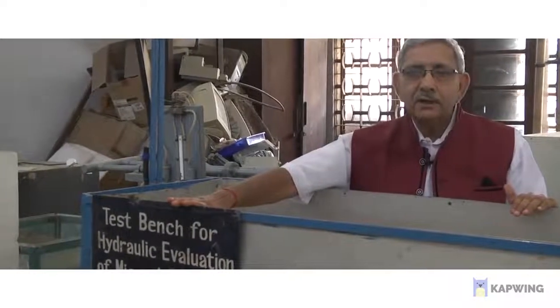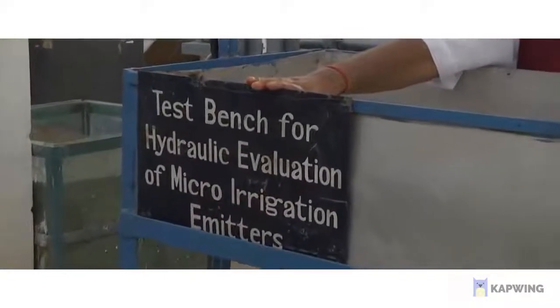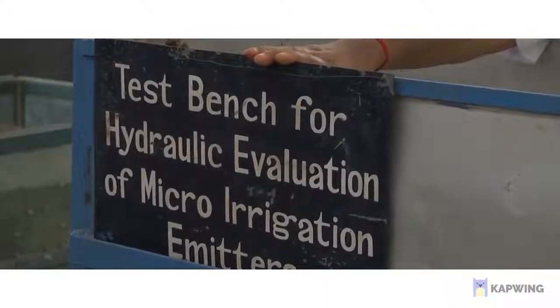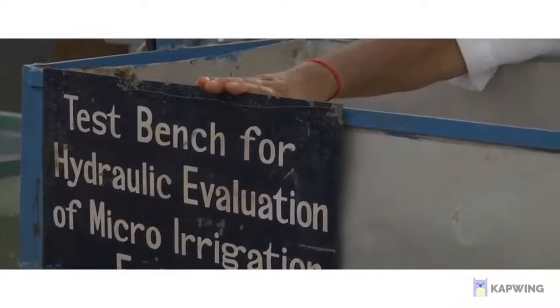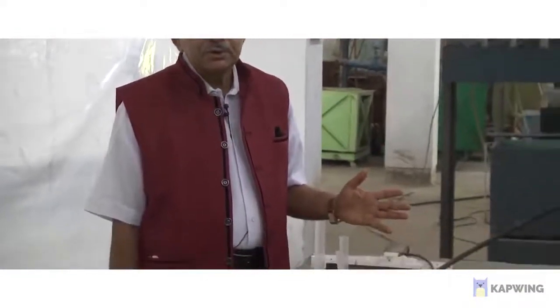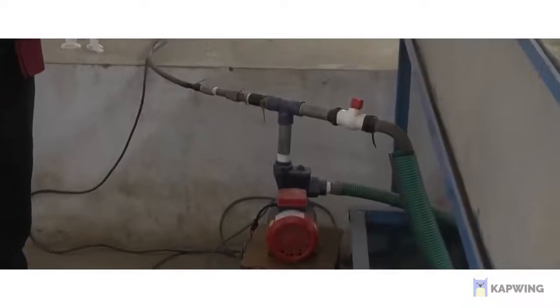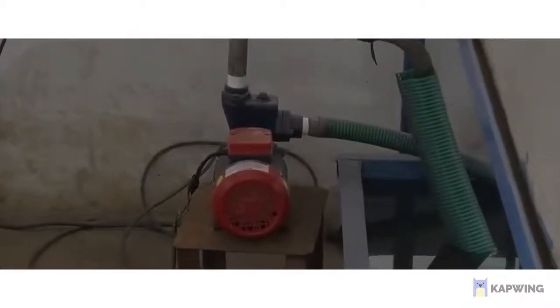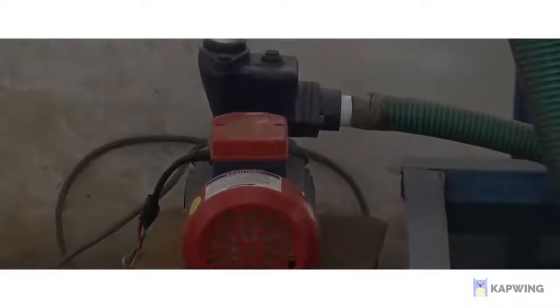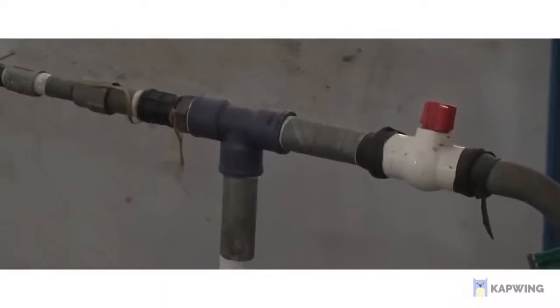This is a hydraulic test bench for evaluation of drip emitters. This hydraulic test bench is meant for finding out the emission uniformity of drip emitters. So, a pump is used to collect water from the source, then water comes through a set of drip irrigation filters, then it goes to the main pipeline, and from the main pipeline it goes to the sub main and lateral pipeline.